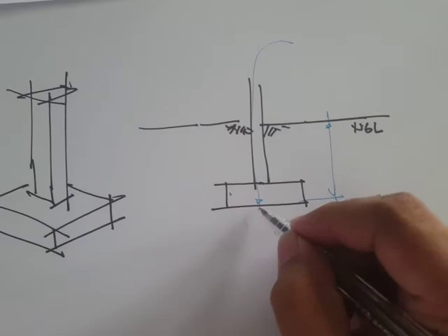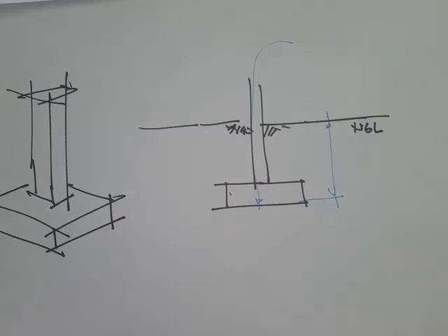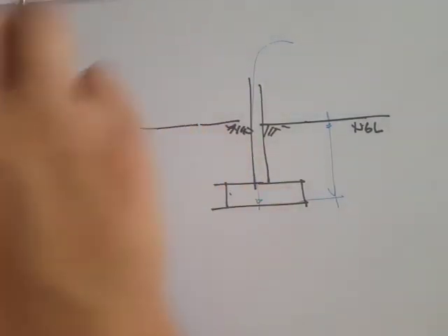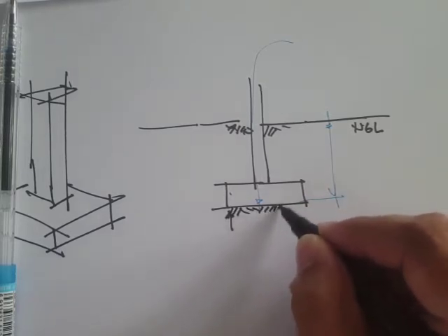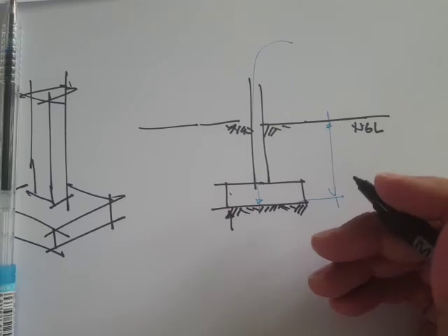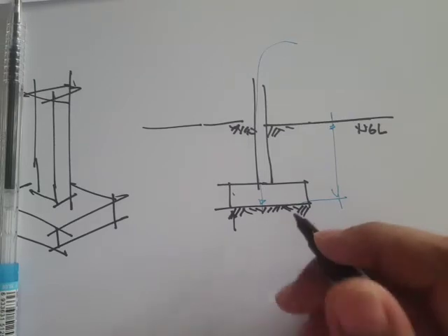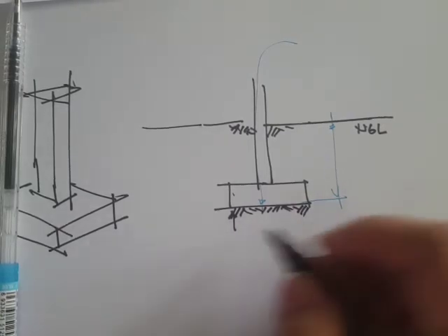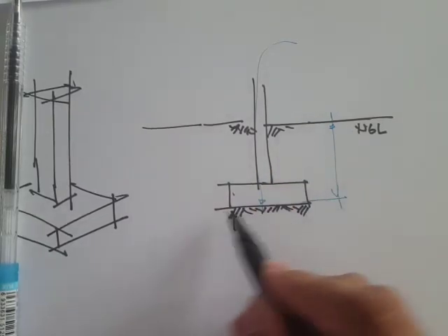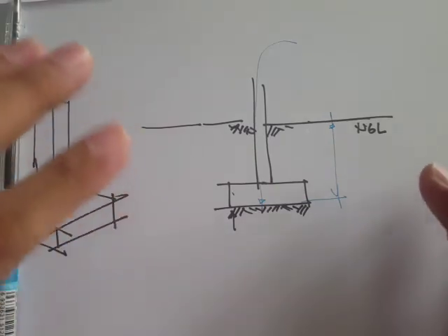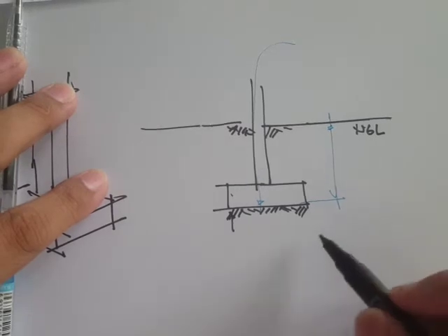So the footings are designed to carry the loads by the supported soils, because the soil actually has some strength, but probably smaller compared to the strength of steel, reinforced concrete and timber. So they are designed to spread the forces, so that has to be compensated in the area of the footing.